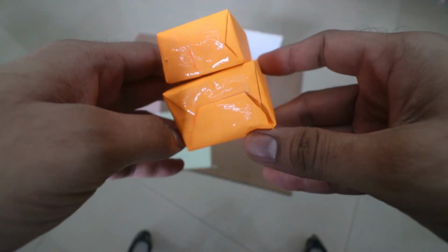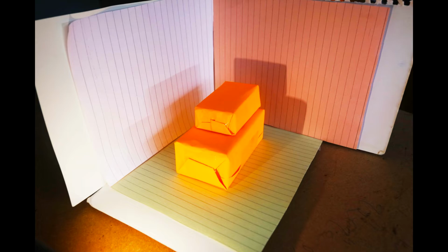In an orthographic projection, as mentioned, we utilize three views of the object. The three views are mutually perpendicular to each other. For easy understanding, we have color coded the three views. White represents the front view, green represents the top view, and pink represents the side view. We place the object in this grid, and to visualize the projection, we take an image or a photograph from each of these directions, that is, the front, the side, and the top.